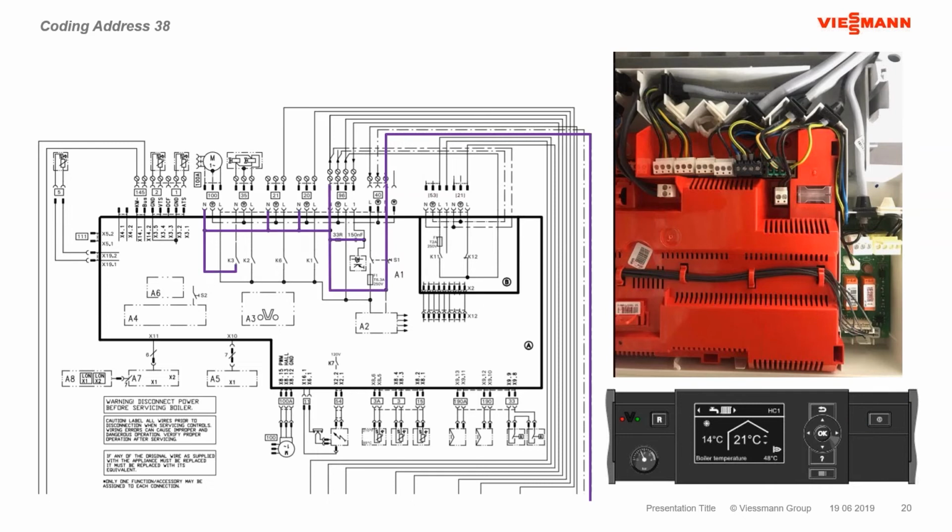So with Mark's assistance, the switch is on, and you see that neutral now ties off to all of the different components on the burner. So everything from your burner fan, your gas valve, some pump relay outputs, 21 and 20. And then it comes up to the 96 plug that sits just to the left of that 40 plug.